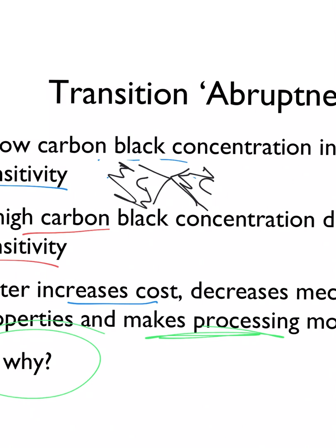You could get more concentrated regions of carbon, causing decreased mechanical properties. Yeah, that's also true. So you have this issue. We talked about this before, how you reinforce plastics with inorganics, and if you don't know what you're doing, you can make the properties worse than when you started out. So if you have too high concentration, then you have bad interfaces or something. You make it weaker. But in the context of processing, I want that stuff to flow down these tiny little pipes. So we have this big melt pool, has to flow down a tiny little pipe and get into a tiny little mold and make this tiny little part.